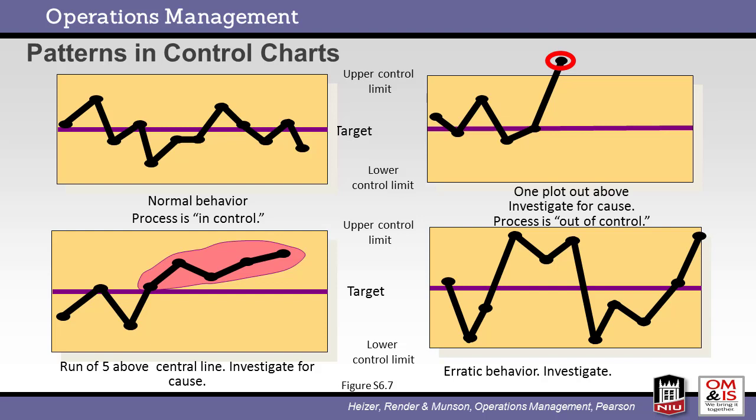The chart in the lower left shows a process that is under control, but has a trend suggesting that the process will be out of control soon. Proactive steps are needed to reverse this trend. Finally, the process chart in the lower right corner is under control, but should be checked because the points vary wildly. This suggests a process likely to go out of control. In summary, 3 of the 4 processes are under control graphically, but 2 of these require further investigation.